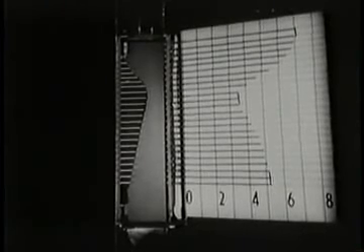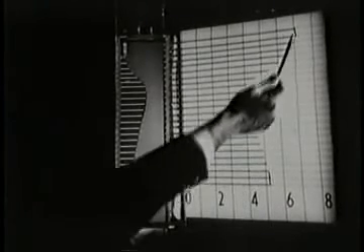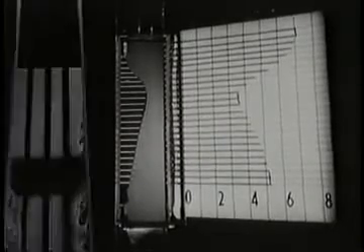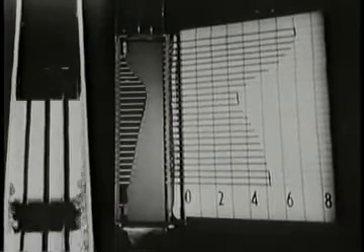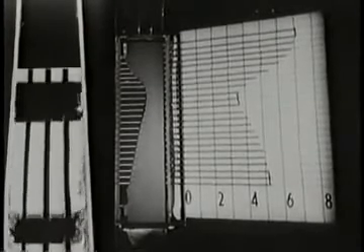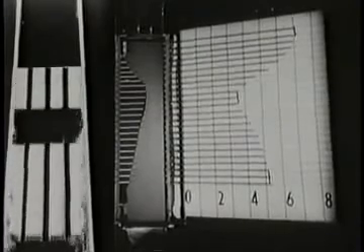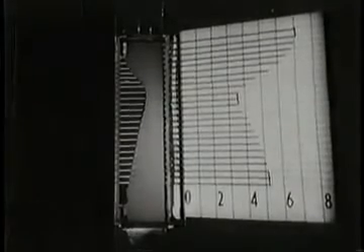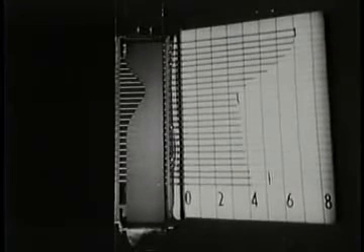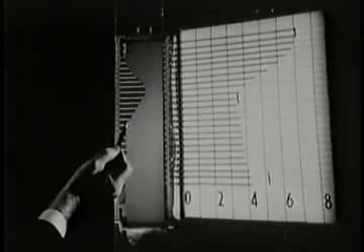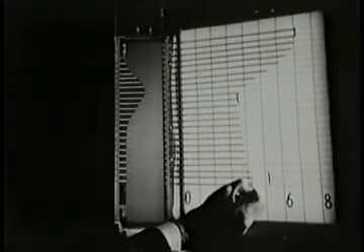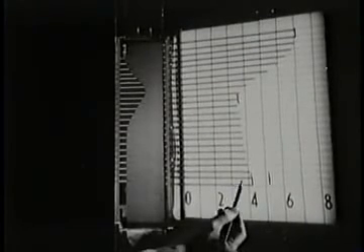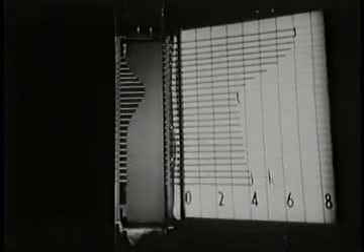This difference is due to viscous boundary layers, whose behavior we must always keep in mind, even when we pretend viscosity is absent. For instance, the area divergence here is much too rapid, and there is very little static pressure recovery in the diffuser. Far less than before. Even a very small amount of viscosity, if it leads to boundary layer separation, can produce very large changes from a truly non-viscous situation.